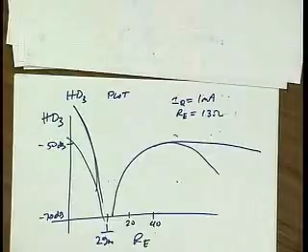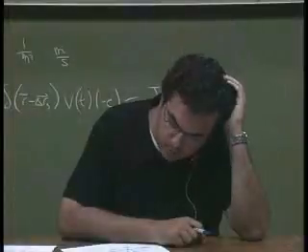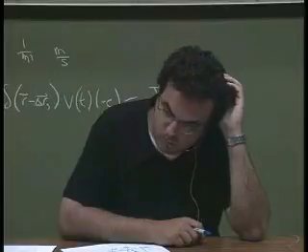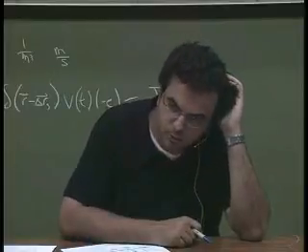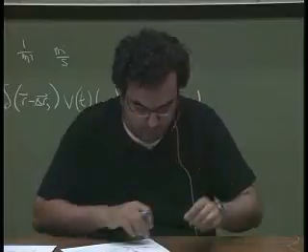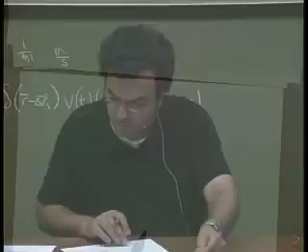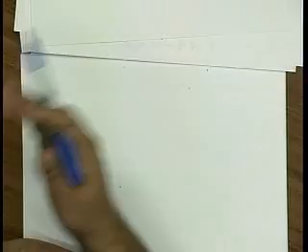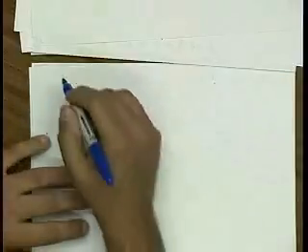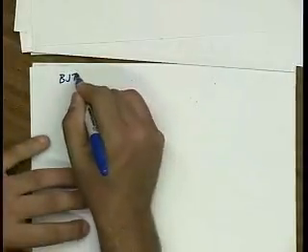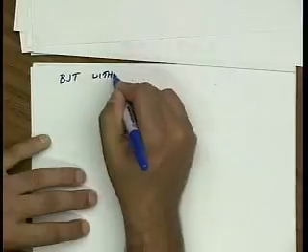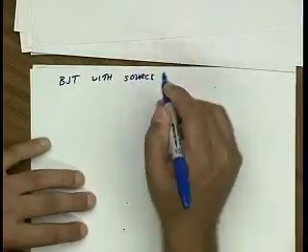Question? Can't you do the RE with some kind of a diode-connected BJT over there, because then you will get your temperature matching and so on? That's what people do. Yeah. If you ever look at schematics of op amps and things like that, you see weird diodes hooked up to the emitters, and you wonder, why are they putting diodes in the emitters? Well, that's the answer.